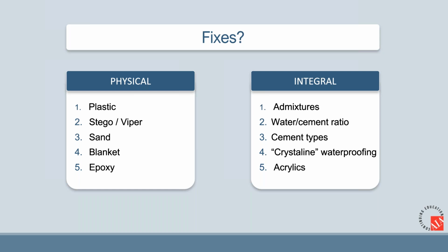The ACI has argued for years on where the sand bed goes. Does it go on top of the poly or below the poly? We would love to water cure every job, but we know we can't really effectively do so. So we started to allow blankets and diapers and burlaps to be applied. And here's where we are in the spec world today. This is what I see almost on a daily basis.